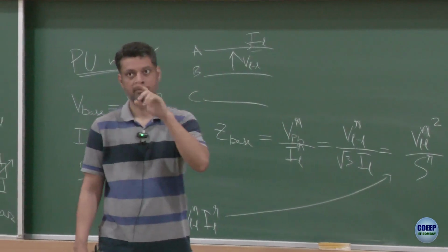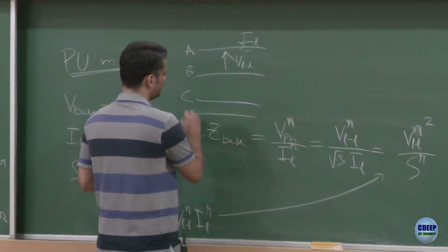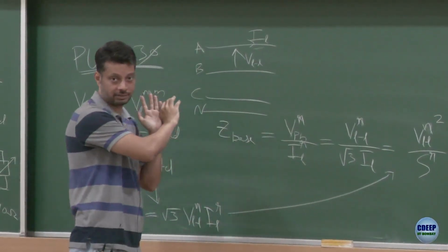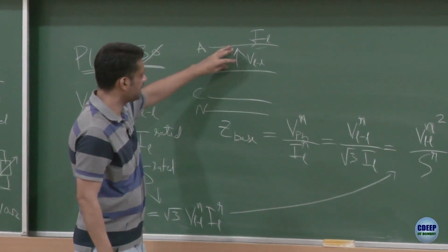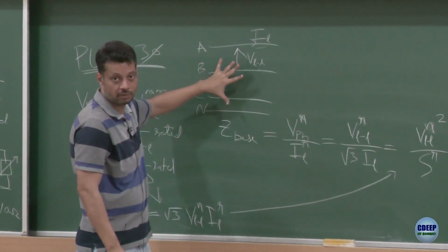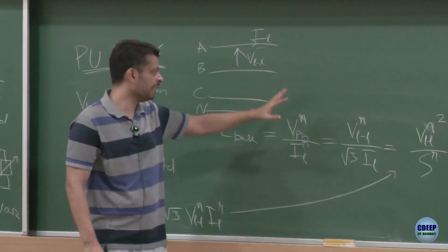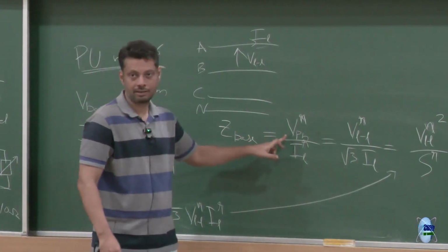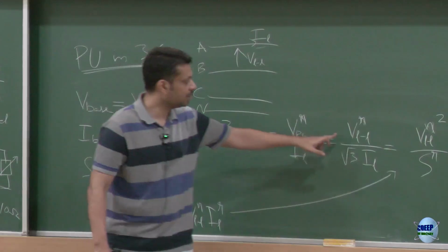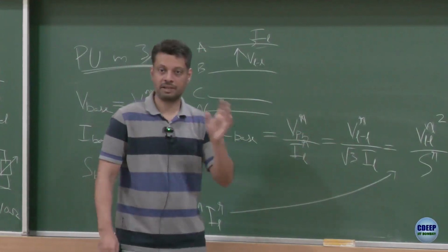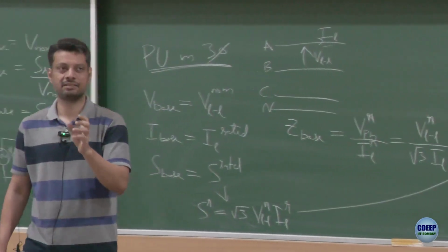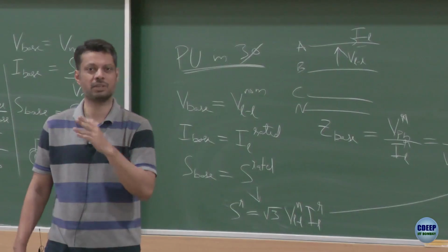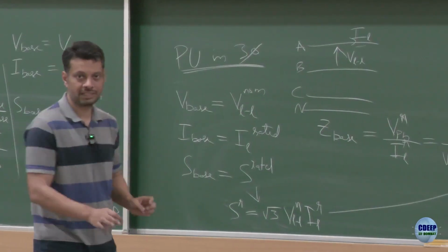So again, if you remember, this is your system. You can have load connected in some fashion, source connected in some fashion, right? The way we are defining is this is line to line voltage and this is phase voltage, VAN. Now if load is delta, N will not connect. I would not call that thing a phase voltage. That is not what I mean here. What I mean here is line to line by root 3. So even if you see from the beginning, that nomenclature saying that delta is a phase voltage and therefore in delta connected system you have line voltage equal to phase voltage, that's the reason I am trying to avoid it, because it does add to confusion.